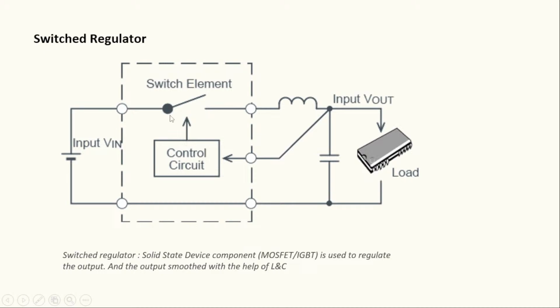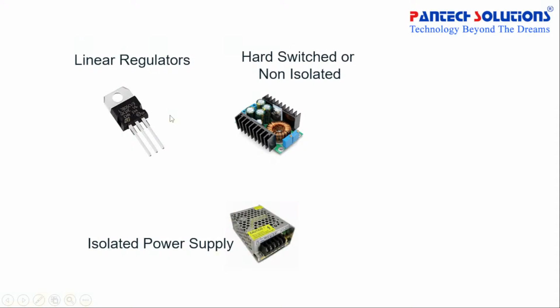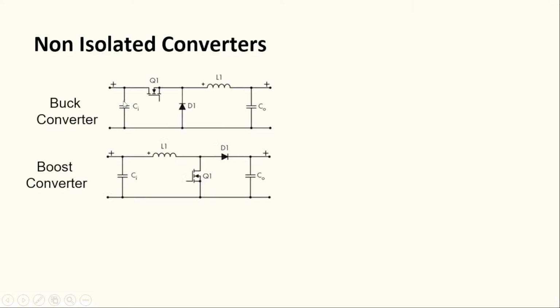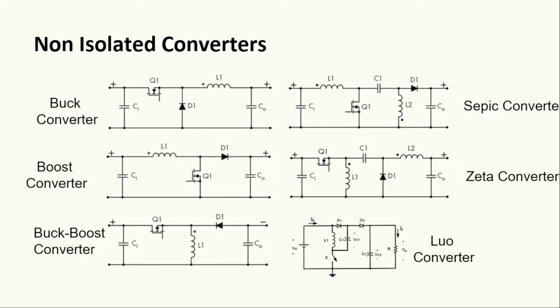Here the linear switch, what type of switch we have to choose? Here I am choosing a MOSFET switch, right? See, you just observe this circuit diagram as the first circuit diagram. It's a non-isolated buck converter. You know what buck means: it's a stepping down converter.